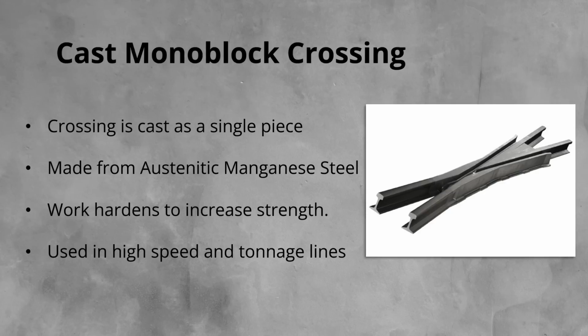They do, however, have some drawbacks and limitations. Firstly, AMS cannot be directly welded to the normal grade steel. To solve this, a small stainless steel insert is welded between the AMS and normal grade steels. This is completed at the manufacturer rather than on site. Defects in this area are tricky to weld repair, given the 3 different metal types within a small area, and often the weld repairs fail.